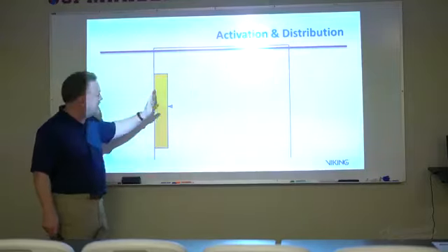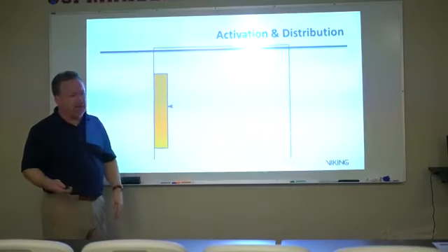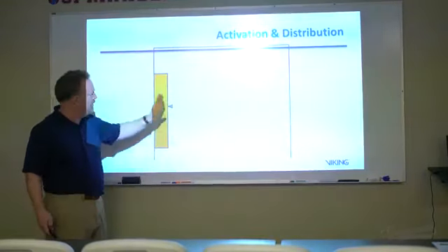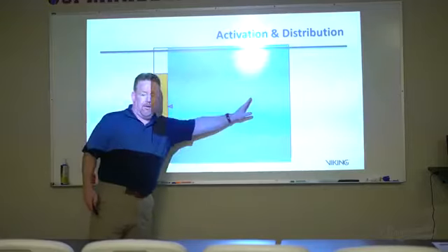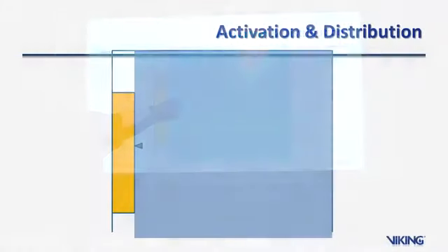So if I've got a sidewall sprinkler, where's the spray pattern going? From here, over, right? Now on paper, what does this look like? A shadow area, a space that's not going to get any water in.